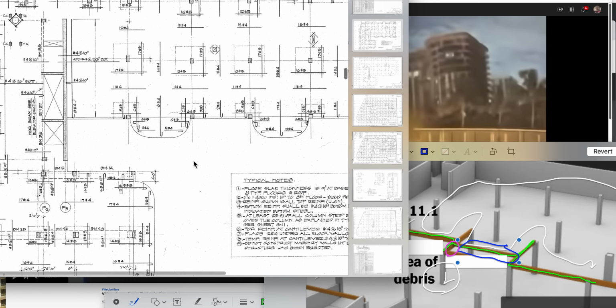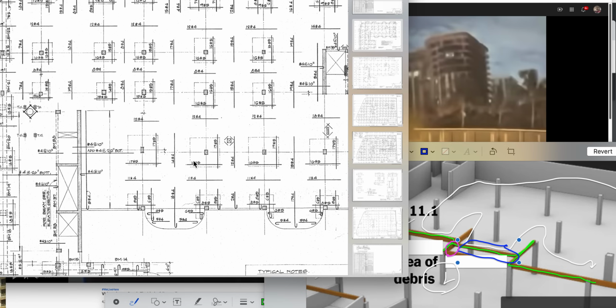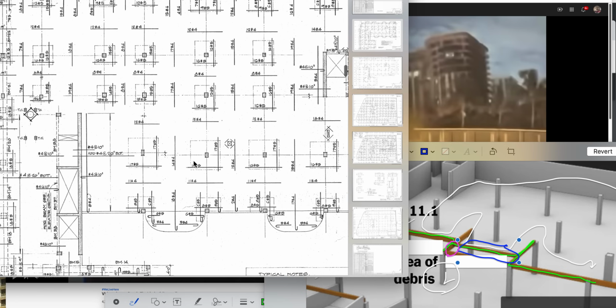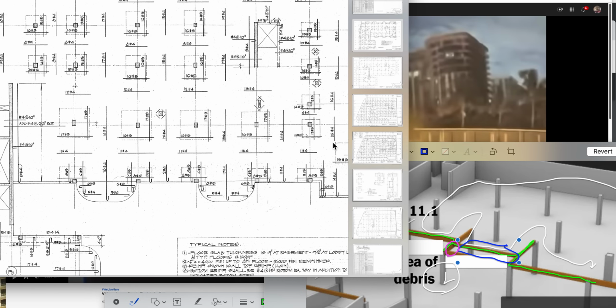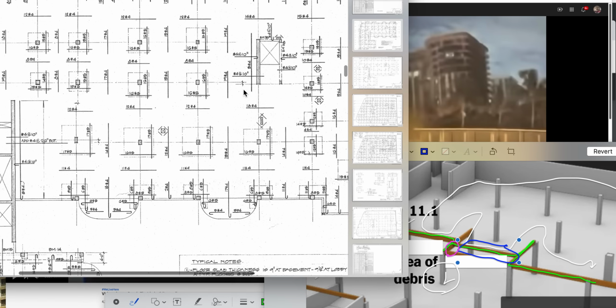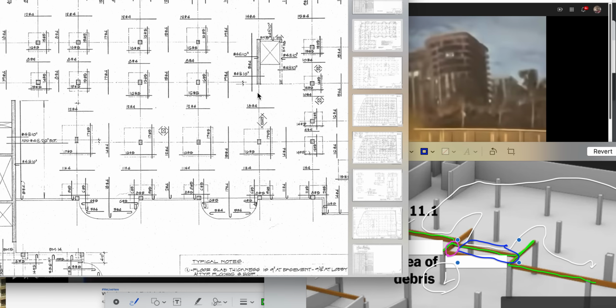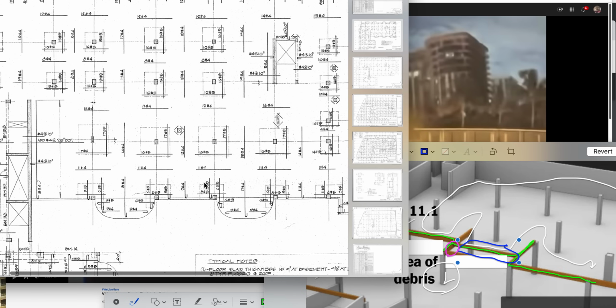All right, going back to I, K, L, M. As we watch over here, this is disengaging, and some of it's ripping out, some of it's tugging, and a lot of it finally breaks free as it makes its way probably over to this shear wall here. It probably does pretty good for a moment there before, as I talked about in the previous video, it takes out the H-beam at the bottom, and the building tilts forward, and it collapses from the bottom up.